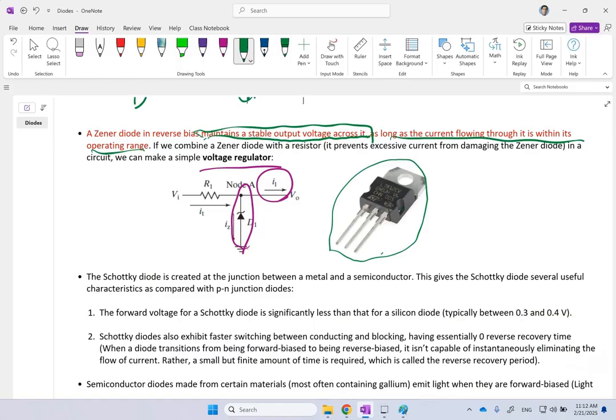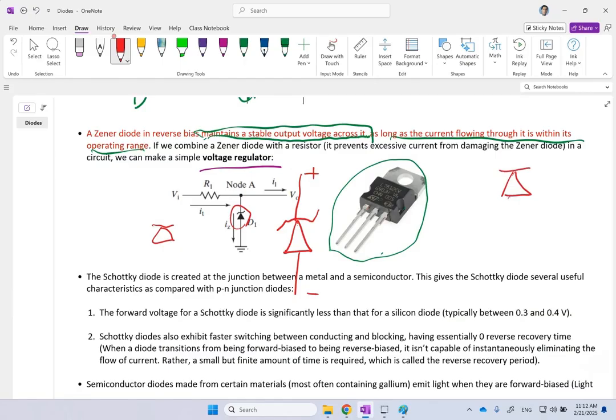So the voltage regulator is typically made of diodes and Zener diodes. Now, one thing I want you to pay attention to is the symbol of a Zener diode is like that. So it's not like a straight line and the triangle. It's basically this kind of broken line. And if you look at it, the way that the voltage is applied is in the reverse direction. Remember, for a diode, if it was like this, you should have applied the positive here and the negative here to flow in this direction. But for the Zener, it is in backward direction to operate. So you see it is in reverse bias that it is connected. Okay, so that is a Zener diode.